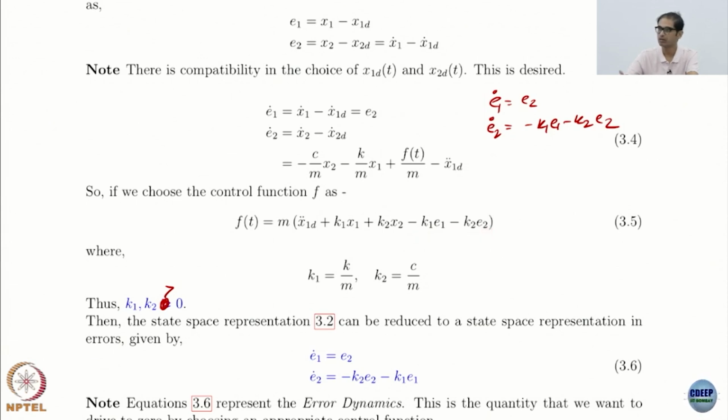PD control, okay. If you do not have a feed forward term and you do not have any idea what your feed forward term is supposed to look like, then you have to have an integral term, okay. So, if you are not doing good, this is the standard principle by which control folks work. Why does integral term work? Because it reduces your steady state error, right.